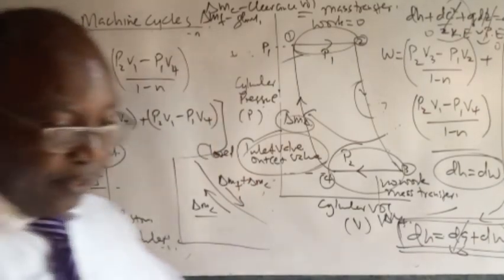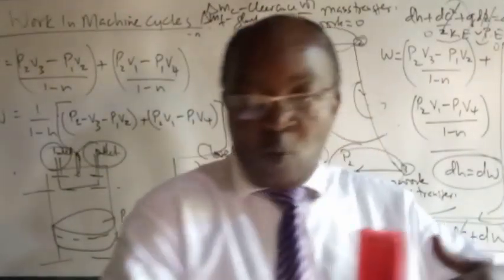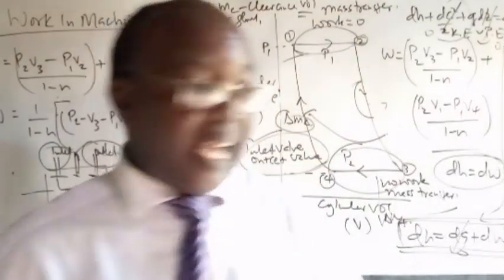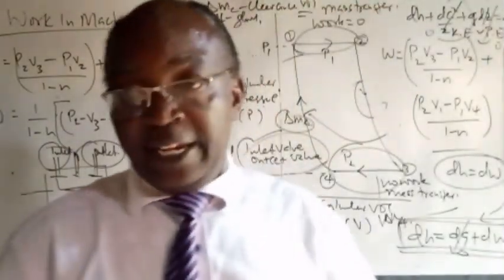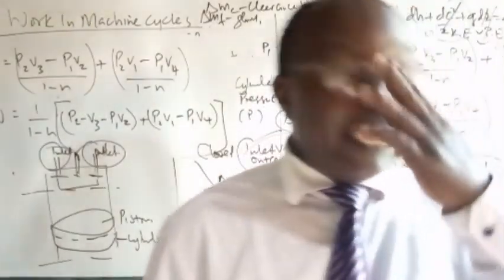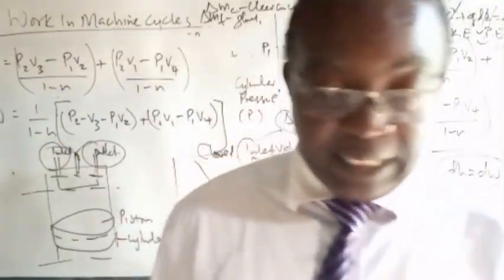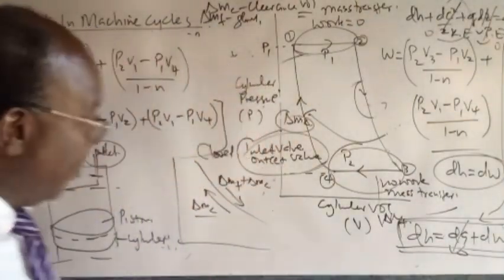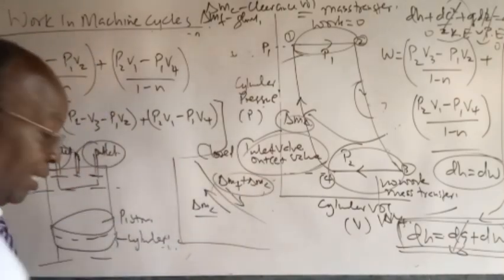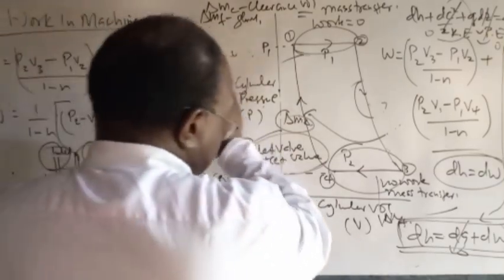So basically, these fluids just move in the process of expansion and compression. The one which is in the clearance volume, that fluid does no work and no work is done on it. It is really inconsequential. It only affects the engine in terms of the capacity of the engine. So up to that particular point, you can always use also these masses, if you so wish, by realizing some very simple and important element,